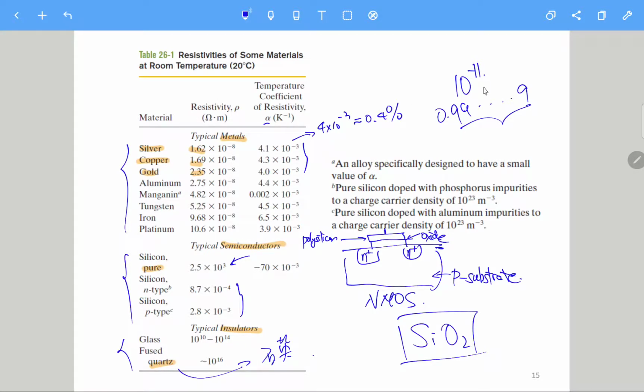And in this case, as you know, silicon has 4 valence electrons, 4个价电子. So in this case, the conductivity is very low, like carbon. And how to make it N-type? We try to add some 5A element to it, so that it will have one more electron at the valence band.